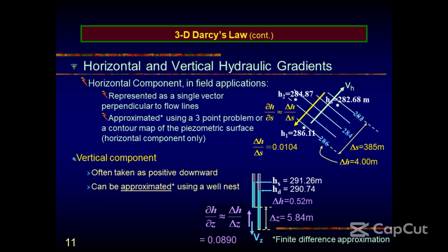Because you just dig a well and probably the level is about, let's say, 0.5 centimeter thickness of the hydrocarbon in your test well. So how do you now calculate the volume of that hydrocarbon within that aquifer based on the depth of the hydrocarbon within the well?